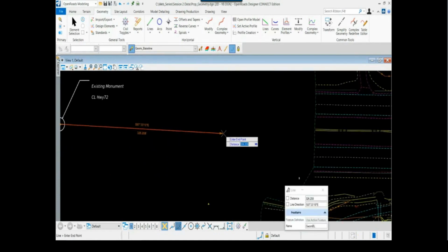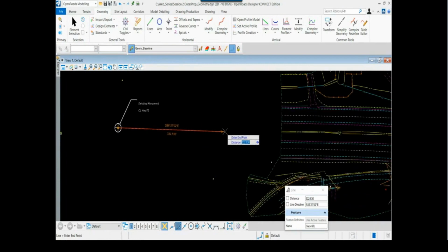And you'll notice as you draw that element, you've got heads-up prompts. You'll notice those on the cursor. And I'll try and explain those. On those heads-up prompts, number one, you can key into the highlighted field, as well as the arrows indicate that I can move between information, left or right. So I click the left arrow or the right arrow, and it tabs me through distance and direction that I can use to input data for this particular element. All right? So I'm going to leave it on distance, and I'll just jump back over to this PDF.